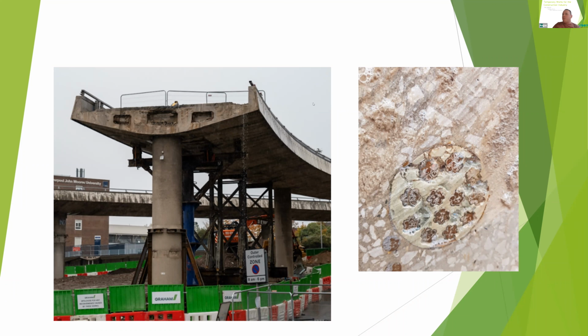This is fairly typical of a post-tension structure. You look at this and you think, yeah, that's probably post-tensioned. Voids within it as well. Fairly thin webs relative to the size of the structure. And as we slice through here with a wire saw, this is the face of one of the tendons. You can actually see here where we've cut through.